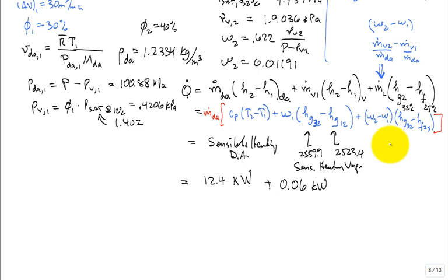The next one, though, is mainly due to the vaporization of the liquid that comes in, but it's vaporized at 25, and then it's heated a little bit from 25 to 32, but it's primarily the latent heating of that liquid. What do you mean by latent? Well, it's an old term, but still used out there. Sensible: if I add some heat, the temperature changes. Latent means hidden, and if I add some heat, the temperature doesn't change. So it's like hidden heat. Well, why didn't the temperature change? Because it was going into changing the phase, going from liquid to vapor. So anytime you have phase change, they talk about, oh, that's a latent heat component. So the liquid that you added in just vaporized? It vaporized, and then there's still a little bit of sensible heat because it vaporized at 25, and then from 25 to 32. But I'm going to just lump it and call it all latent.